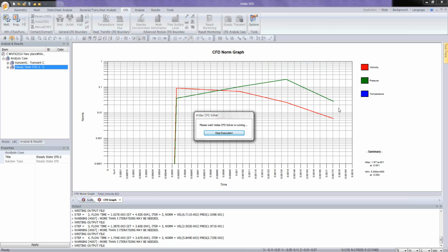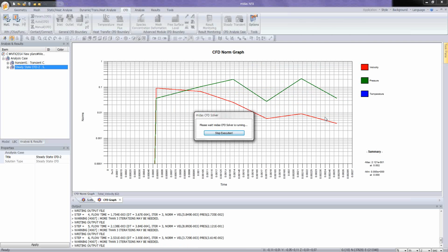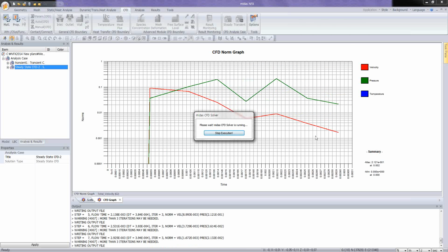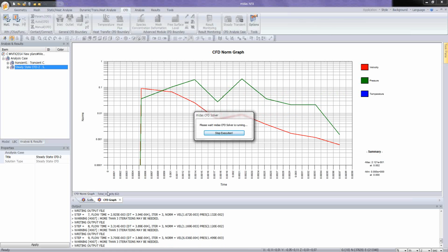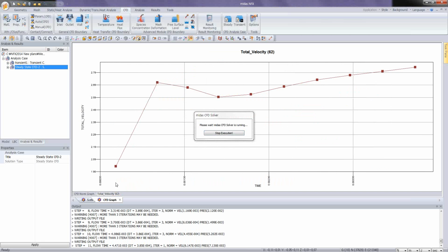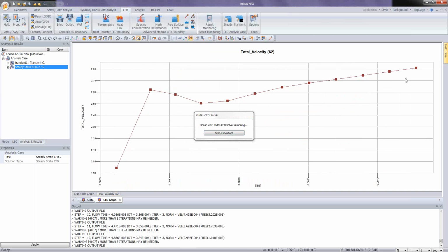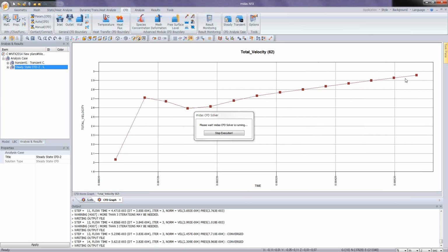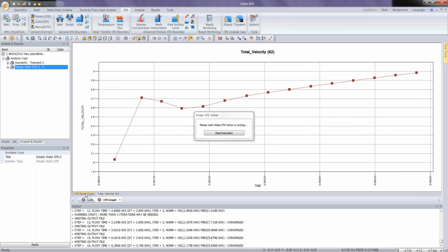So you have the convergence graph. You have two values, the velocity and the pressure, and when they reach a value inferior to 0.001, I have the convergence. So I have to wait a bit until it converges at least. This is the value I am monitoring, the velocity at the outlet. So here I have the value, and I know exactly when I need to stop this steady state analysis, when this velocity reaches a steady state, so when it is stable.